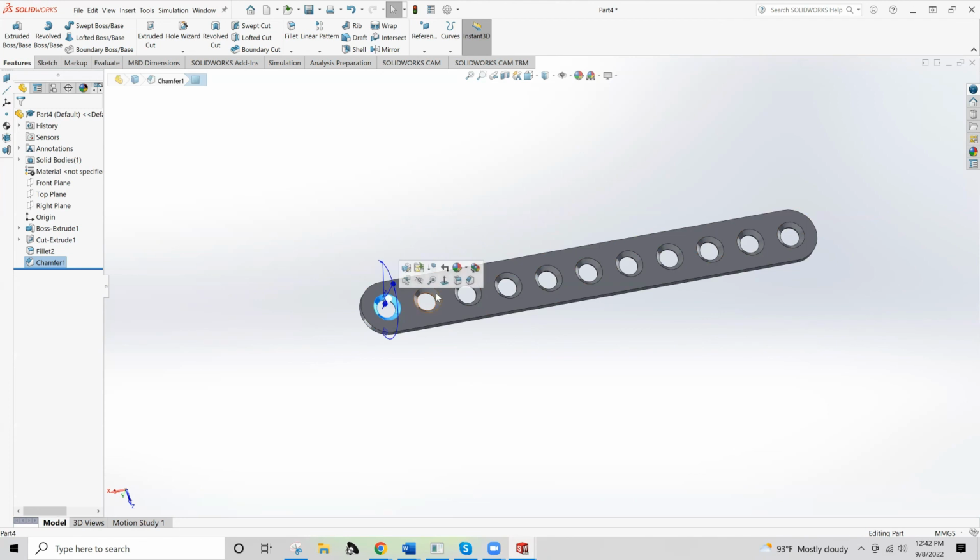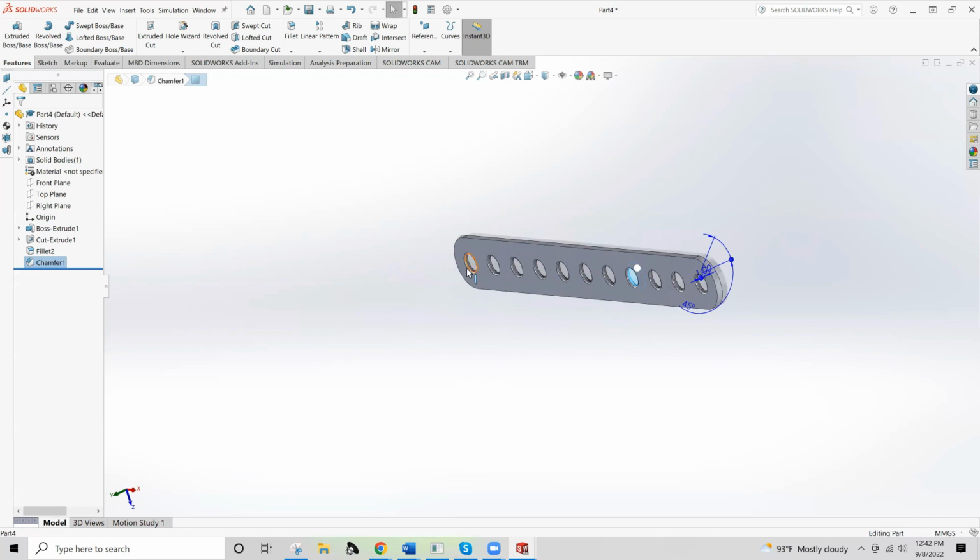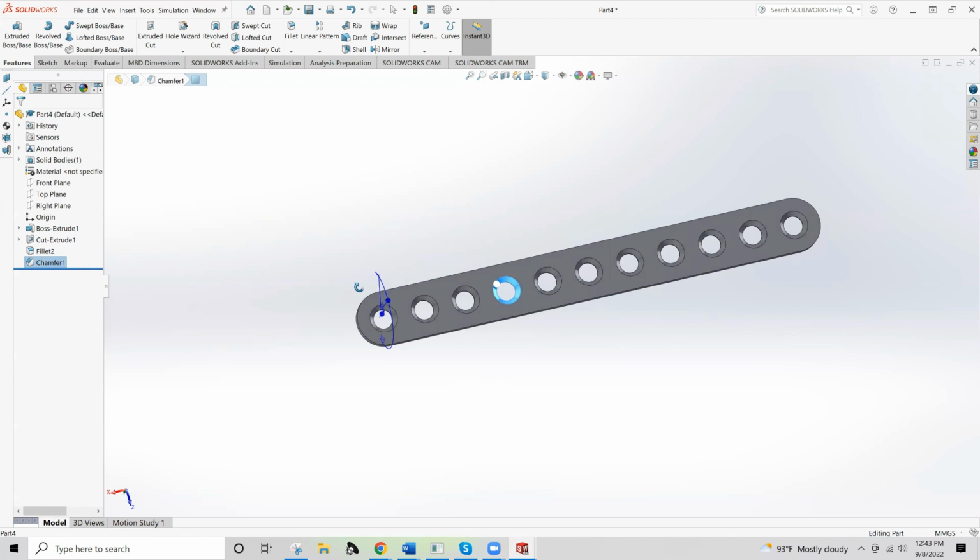So medical implants are often going to have these kinds of chamfers and fillets to make sure that when that metal part is implanted, there's not going to be any machining debris, any burrs, any sharp spots to irritate the tissue around it, because otherwise there would be a lot of swelling for the patient and cause a lot of difficulty.